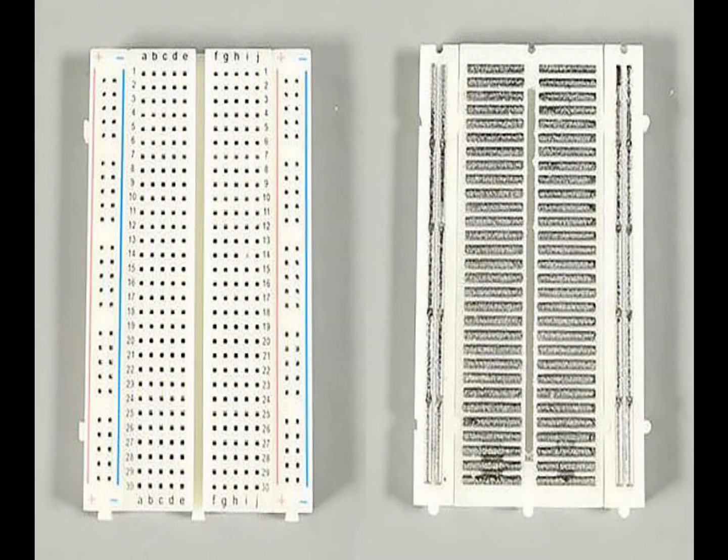If you've never seen one before, you might wonder how to tell which holes do what. It becomes easier to understand what's going on when you see one from the bottom. Seeing it from this perspective makes it easier to understand what is going on. The two larger pieces of wire down each side connect to power sources to the board, referred to as power rails. The other smaller pieces of wire running vertically across the board are used for the components in your circuit. This diagram will help visualize the pattern from the top.